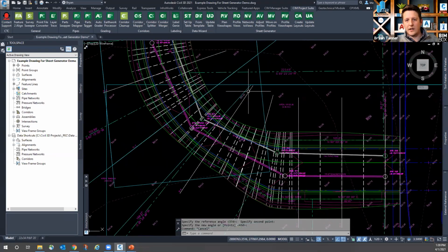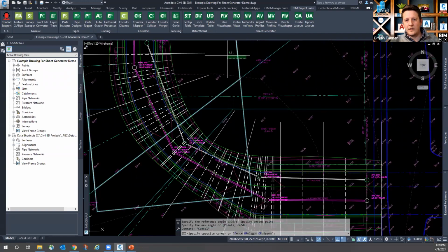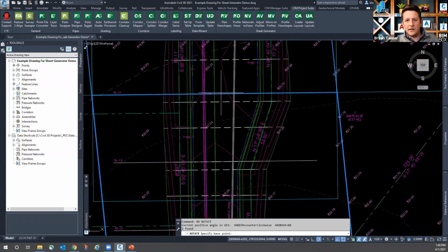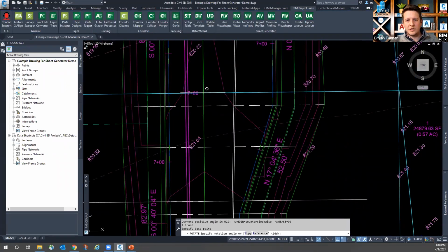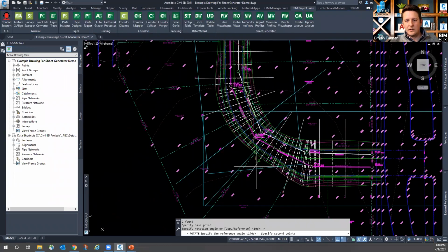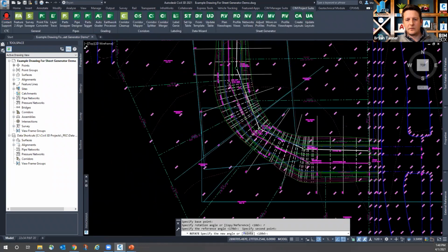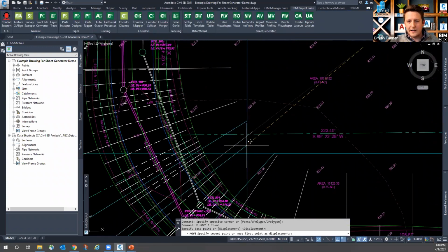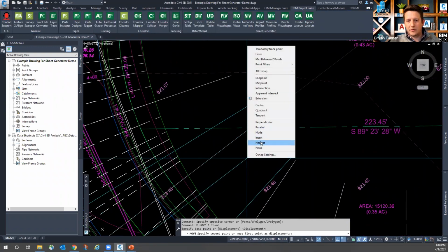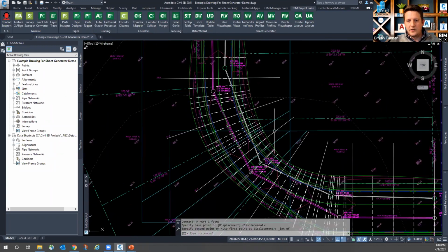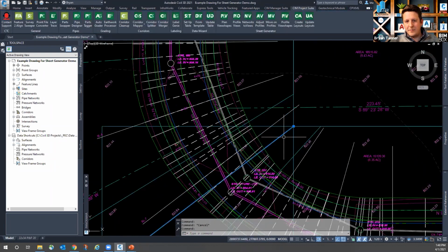And I can come back through and make those adjustments again with the next view shape and its associated information. I can go back to its match line point with the subsequent sheet, and I'll do a reference rotate again to where it's perfectly north-south. I just have better controls over this than I do with the out-of-the-box tools. It's not that the out-of-the-box tools are bad. I just prefer having a little bit more control over it, and we're all familiar with AutoCAD functions. So there's my match line.